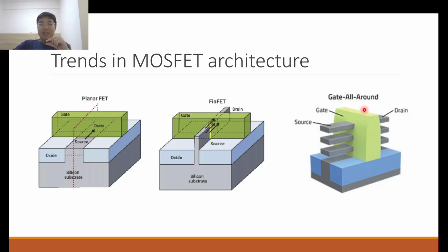From what I know, and there is available information, Samsung is already using the gate all around architecture for their 3 nanometer process nodes. However, of course, the device is much more complex compared to FinFET, because we have these suspended channels, and you have to consider what is below them. How do you get this kind of etch pattern? There are many more complexities related to device fabrication than for the FinFET and the planar FET.